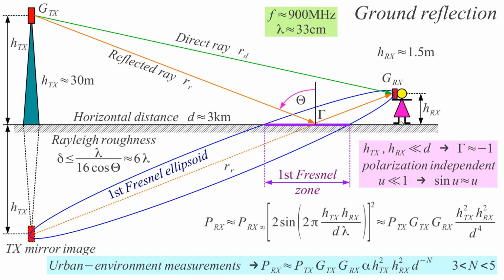So because of this reflection from ground, the signal decays much quicker. And this is actually useful for phone companies, because in this way they can predict where the signal decays, and they can reuse the same frequency channel in another spot without causing harmful interference to these communications from the base stations to the girl here with the mobile phone.